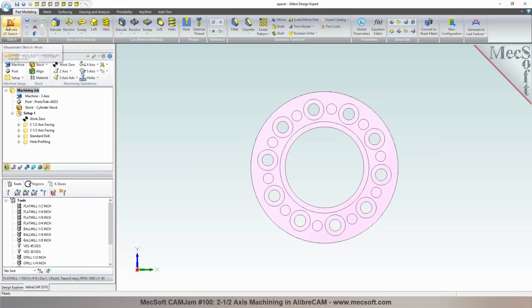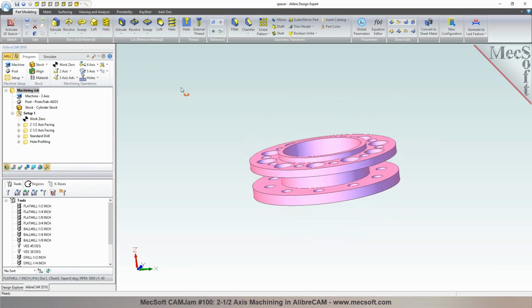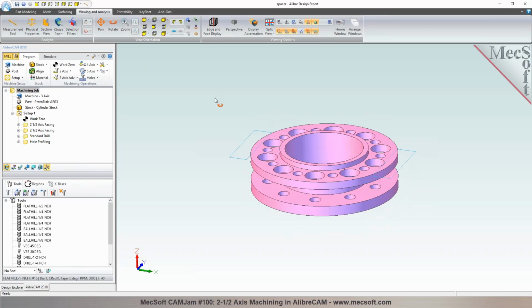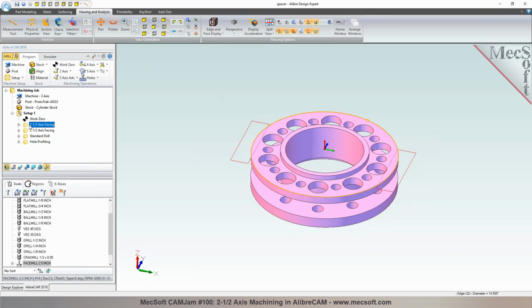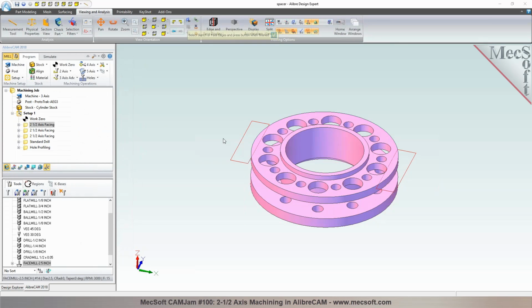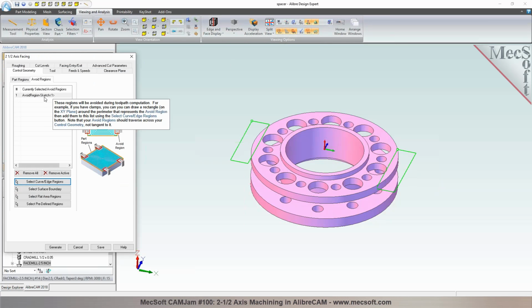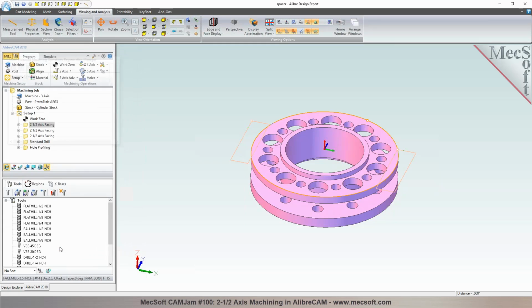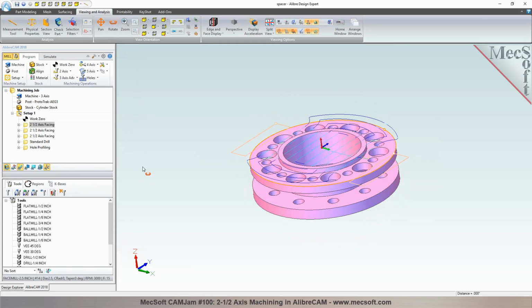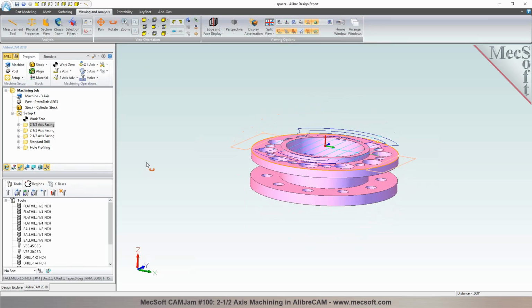So I define a sketch. Now I have the sketch created. Let's display the sketch in here. You see the sketch? Now in the facing operation, I'm going to make a copy of this so you can see the difference between the two. If you go to avoid regions, you can click on select curves, and I can pick that sketch right there. So that's the avoid areas, and then I pick generate. You will now notice that the toolpath automatically excludes those areas.